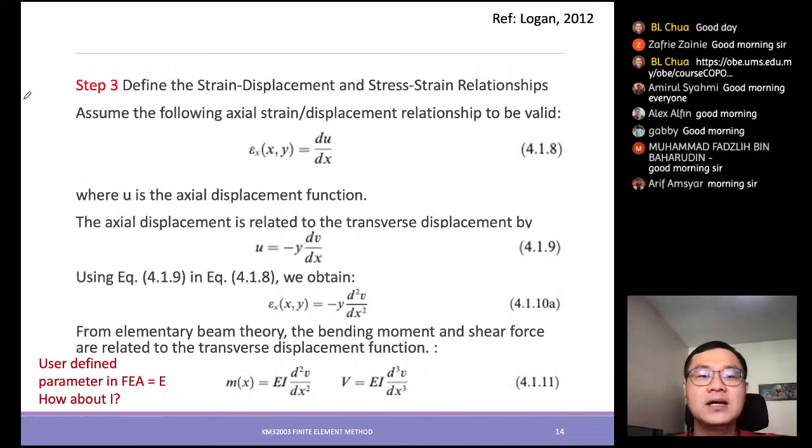Next would be starting with the definitions of stress, strain as well as strain-displacement relationships. What we have derived so far is only related to the displacements across the element itself. So how can we define the strain as well as the stress itself? We apply our relationships. For the beginning, we know that the strain is equal to the displacement divided by the original distance.